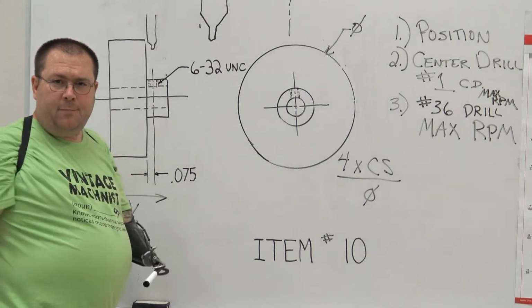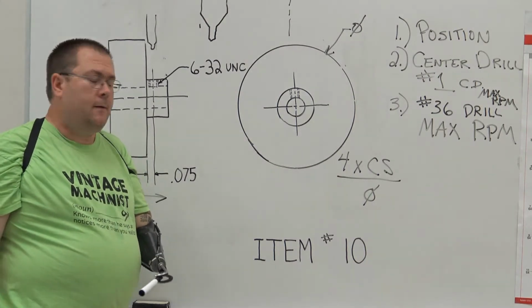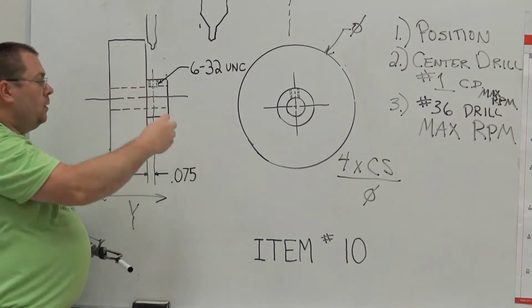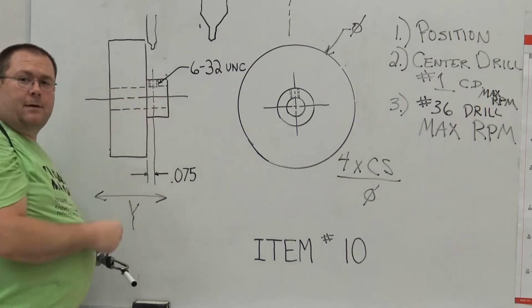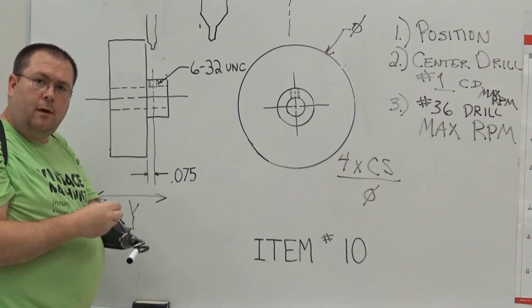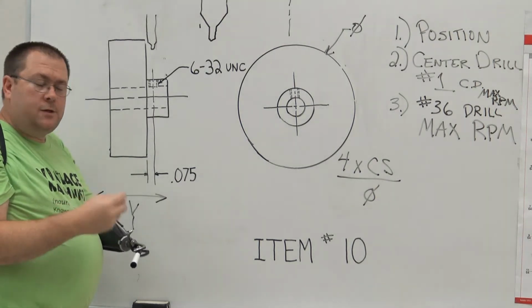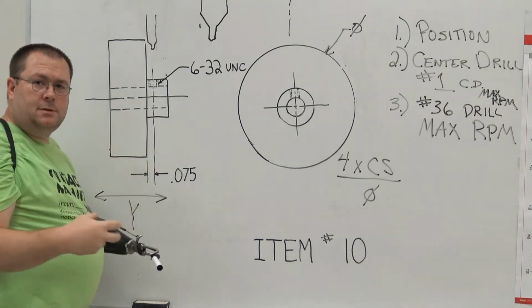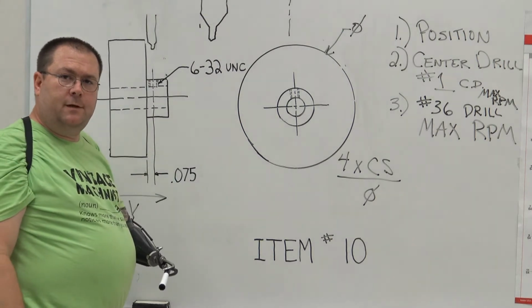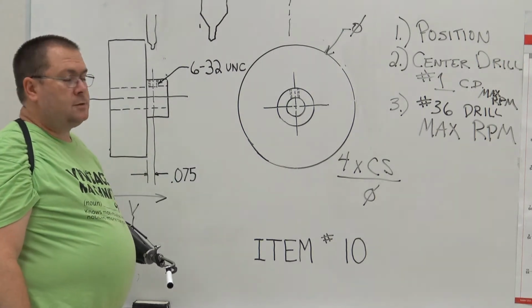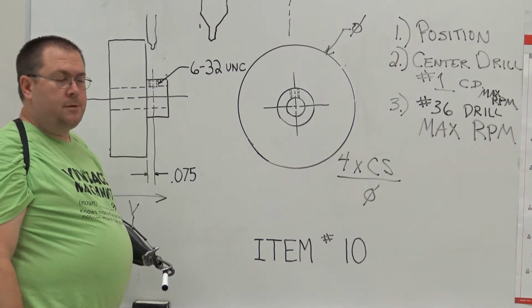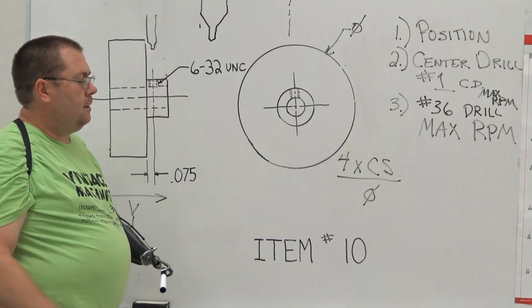So after we tap that hole, right? After we tap it, we're going to take our reamer and feed it back through the hole so that the shaft will run through, okay? And the shaft that runs into the flywheel is the shaft on the back of your crankshaft. You'll see that a lot clearer when we get to the machine, okay?